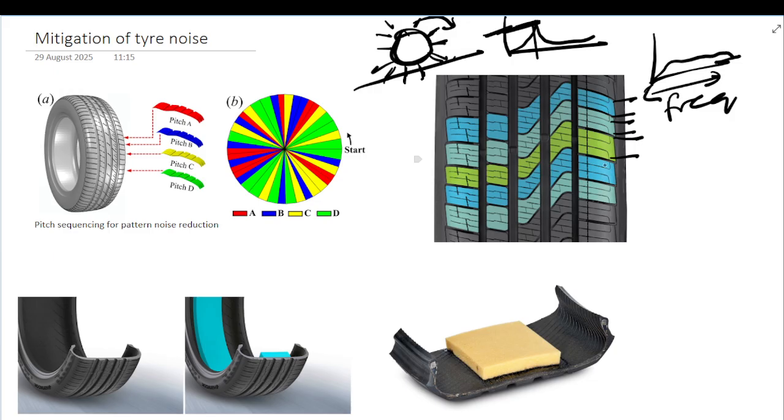So the tire is like this, and you have a rim that is closing this, that is being fitted into the tire. Then you have the air trapped here. So this air also vibrates. So that's why they have added a foam layer here, which reduces the amplitude of this noise. So these are the basic things which are like corrective or design measures that have been taken.